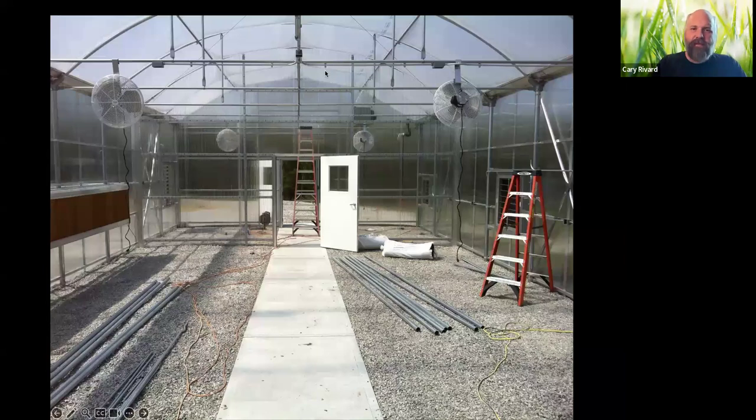Just a comment about glazing and covering. Again, this is a picture of our greenhouse at the research station. One of the things we decided to do was actually put a poly film on the roof. So we have sidewalls and end walls with twin wall polycarb, or rigid plastic, essentially. But we didn't want to do that on the roof. At the time that I bought this greenhouse, it would have added about $20,000 to do that. And it takes me about $1,200 and a calm morning with a few people to replace that roof.